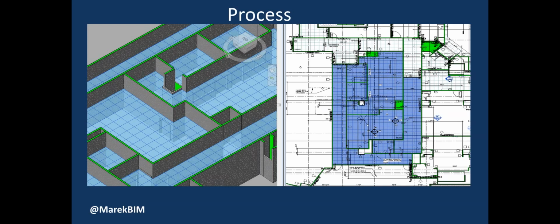And then we start verifying the accuracy of the model. Is it in the proper location? Are the properties of the wall correct, the height, the thicknesses? A 3 5/8 wall with 2 layers of 5/8 on each side is 4 7/8 inch. Sometimes an architect will just make it 4 inches. So we make sure that everything is as it's supposed to be when we build it in the field, so we have the proper dimensions, the proper heights.